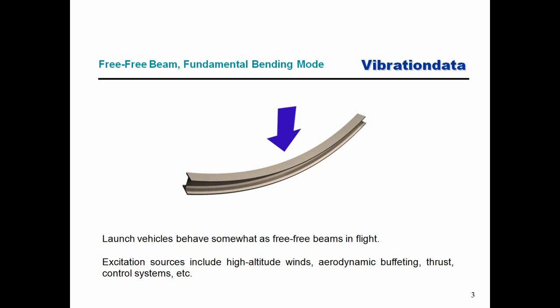And why are we interested in the natural frequencies of these bending modes? Well, typically these are maybe 10 hertz or lower, and that is well below the expected natural frequency of our avionics and our circuit boards and our avionics boxes. So from an avionics point of view, in terms of the applied environments, we're just not that interested.